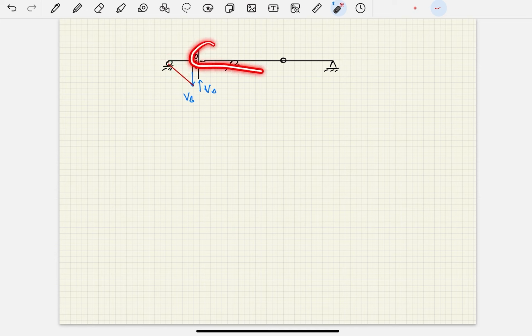Now, what's going to happen with the entire right side? VB rolls this up, and then you have a pivot point here, you're going to develop some kind of kink at D because of that internal hinge, and another pivot point at E. So what this is going to look like is something like this.